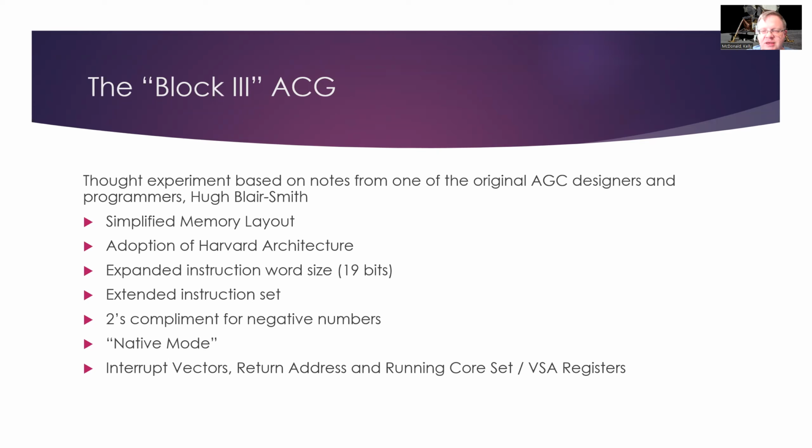One of the reasons I'm designing the computer the way I am, with the circuit boards that I showed in the last session, is to make it very modular, so I can plug cards in and out. If we decide to start expanding or adding new functionality or features, we can pull out one of the old registers, like the S register, which is the 12-bit memory address register in the current Block 2, and put in a new one that has additional bits for larger memory access.